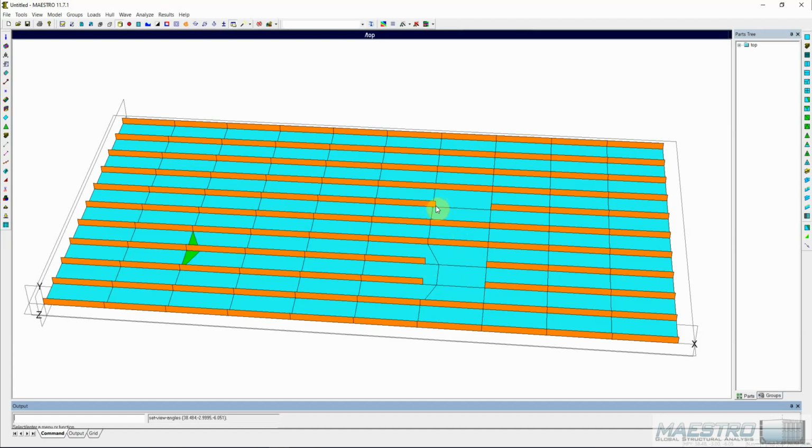Similarly, when we missed that one node from editing the polyline, where it was slightly off, the first segment did get written because the first node had a corresponding mesh vertex, but the second segment was skipped. And the segments where we've inserted an additional mesh vertex, or in the case where we missed one of the mesh vertices when drawing the polyline, you can see because it had a mesh vertex at the beginning, it was able to compute the normal and create the beam. But the user should be aware that when it fails to write a beam segment, there's currently no warnings given.